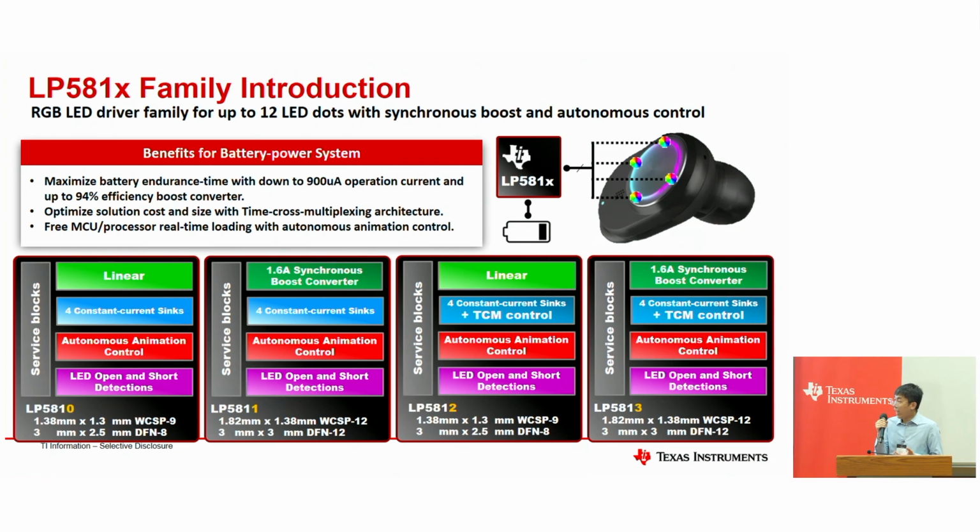So that can cause a really massive load to your MCU, communicating on I2C or SPI. So what we also do on this LED driver chip is add additional digital circuitry in this IC to help you repeat the same animation pattern, so you don't have to constantly repeat sending the data from the MCU to the LED driver, and this can also help save power.